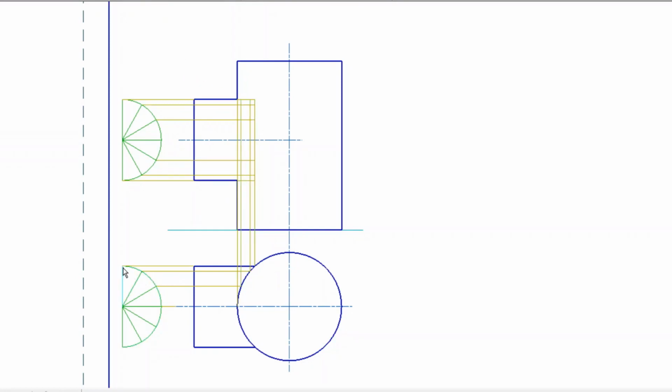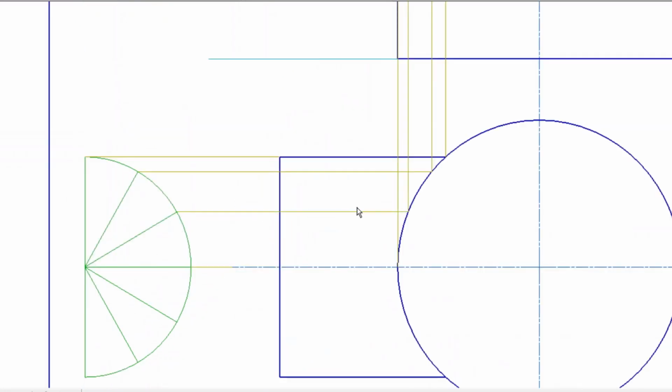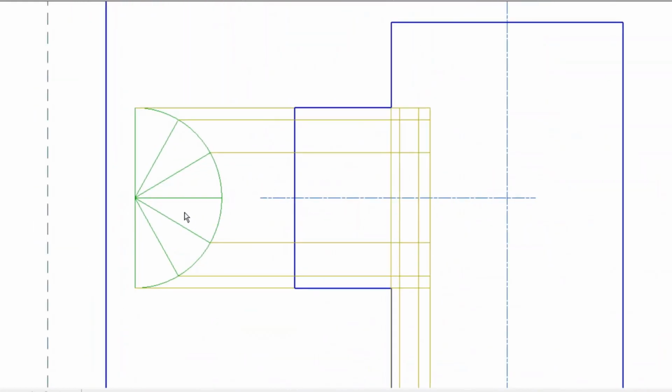You just take your circular base points, so 1, 2, 3. Obviously the one in the middle counts as well, so the center already acts as 1 point. So this is a penetration point. All you do is project the construction line until you hit the line of penetration, and then you take it up to the front view. Then you just repeat by taking the same lines from the same construction circle, which represents the base, and you take them across and you'll get this little grid here.